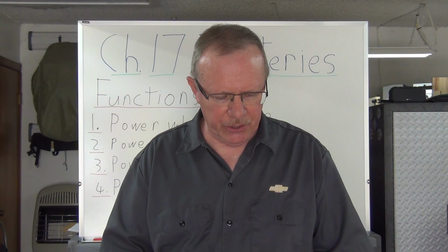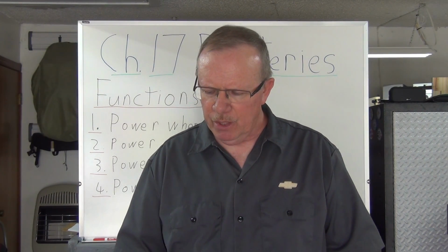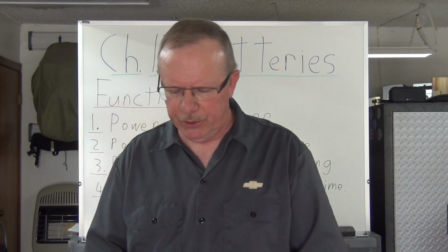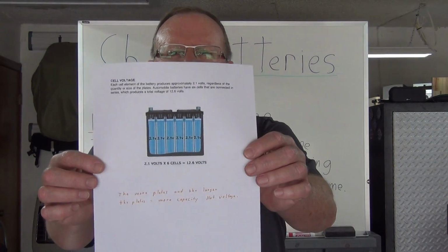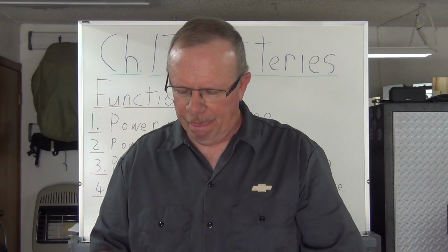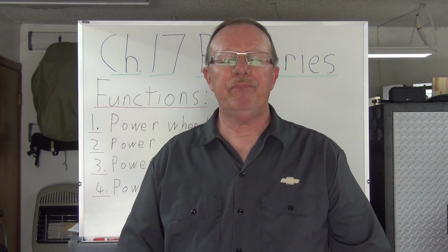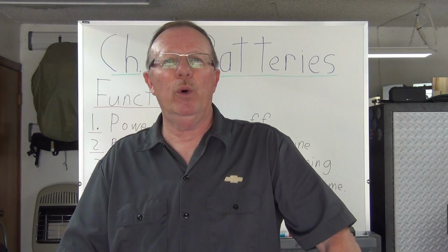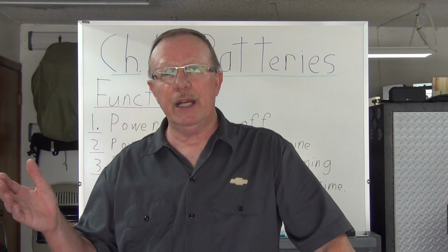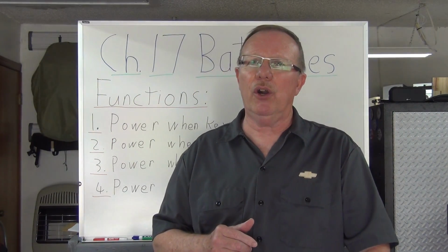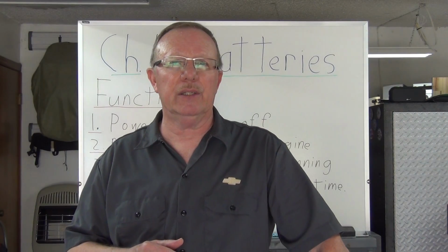We've talked about how things are in series and parallel and so forth, right? So there's a picture there, pretty good picture, 2.1 volts per cell, okay? You put them in series with each other and it just adds it up. So a fully charged lead acid automobile battery is 12.6 volts, technically, okay? And we like to be technical sometimes, right? And so, as we'll see a little later on, there's a reason we do that too. There's ways of telling the state of charge of the battery if it's not at 12.6, and they have charts for that too.